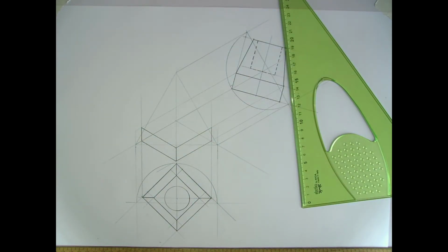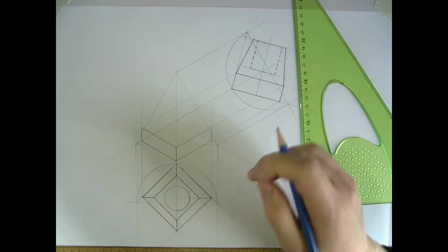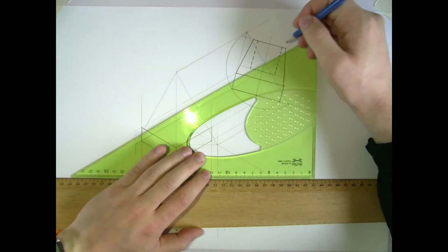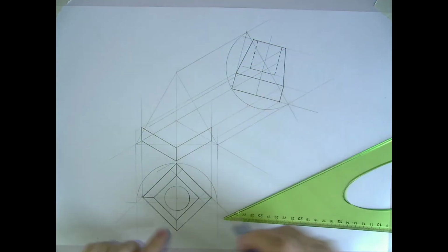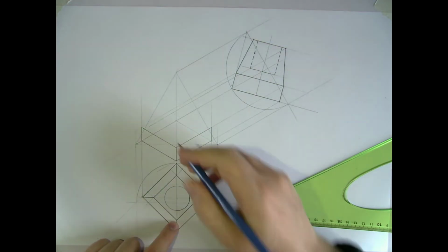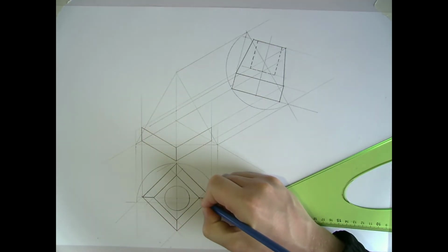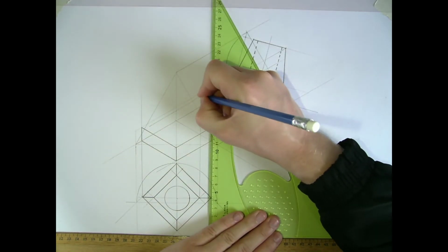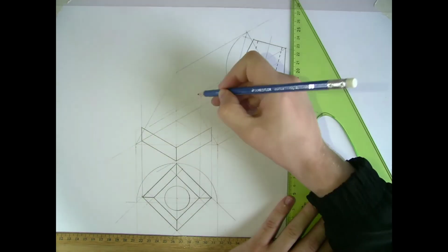The next part we're going to look at drawing the top face without the hole up on top of it, and then we'll be able to put the sides into this. So I'm going to take this top front corner and project that down along. So that is looking at this line along here as an edge view. So that gives me 2 points. That's going to give me this point here and also this one. So that back along further is this point here. So on the line down along here, front point, back point, give me 2 points there.